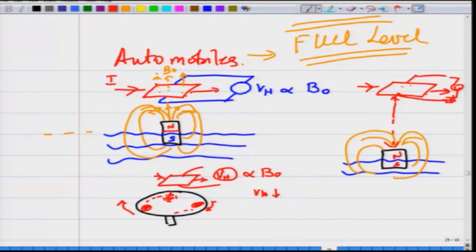So, what is the position of the rotating disc, whether it is at position A or position B, it will immediately know by the polarity. You keep one magnet of one polarity and another magnet of another polarity, and the Hall voltage will also change sign because it depends on the sign of the magnetic field. As a result, you can identify whether position A has come here, or whether the other position has come to that location.